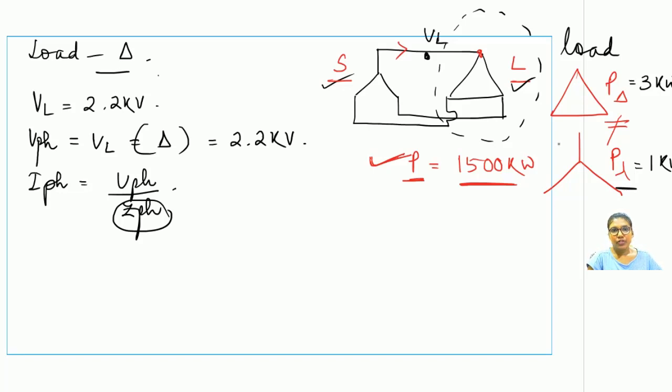In all the previous questions, the load was changing its structure. The load was changing from star to delta or from delta to star. Hence, the power of the circuit on the load end was changing. But in this question, the source is delivering a power to the load. So, irrespective of any connections, whether it is a star or a delta, whatever power is being delivered by the source has to be taken up by the load and there will be no change of power on either end. I hope I have made myself clear.